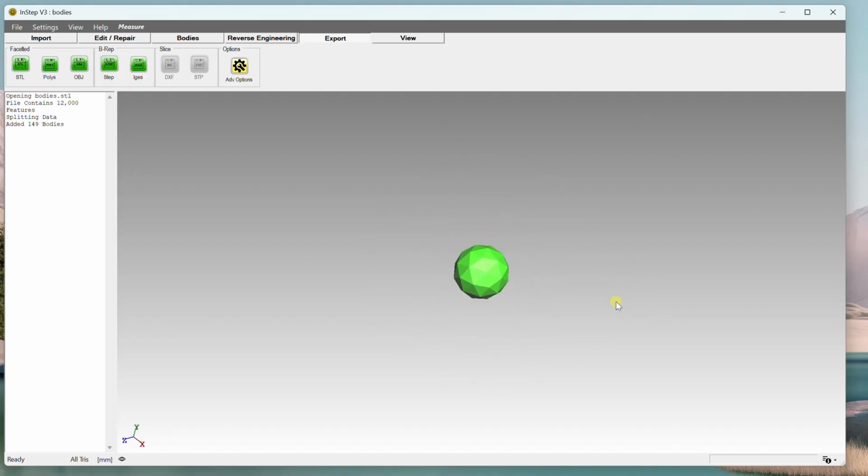The other option you have, and that's kind of built in based on some issues that come up sometimes, is you can use the Control Home key shortcut, and that will do the same as the Home key, but it will also completely redraw all the data from the database. And in this case it's very quick. The bigger the file, the longer it will take, because it actually goes in and grabs all the existing facet data, all the color information, clears the display, and regenerates that.